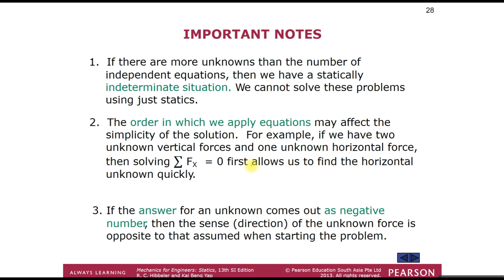Okay. So, important notes: if there are more unknowns than the number of independent equations, then we have a statically indeterminate situation. So we cannot solve these problems using just statics. In order to solve them, we have to apply additional equations that may affect the simplicity of the solution.